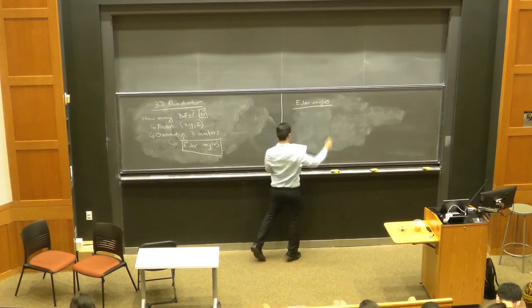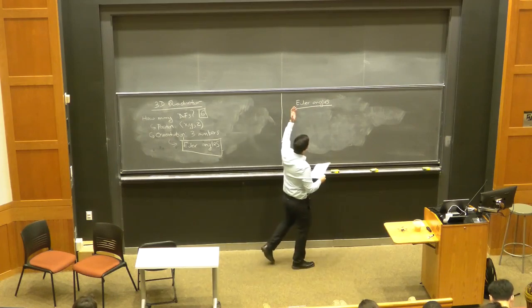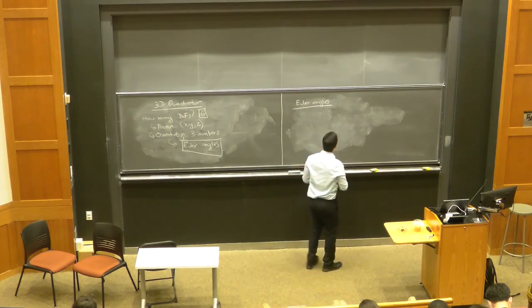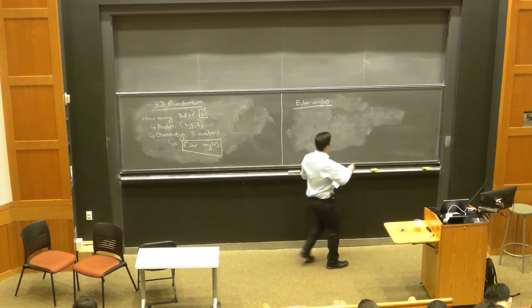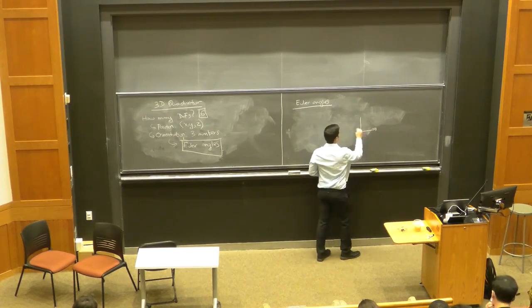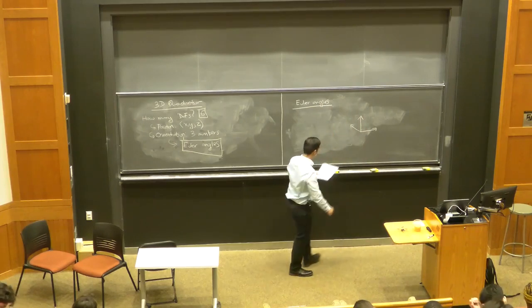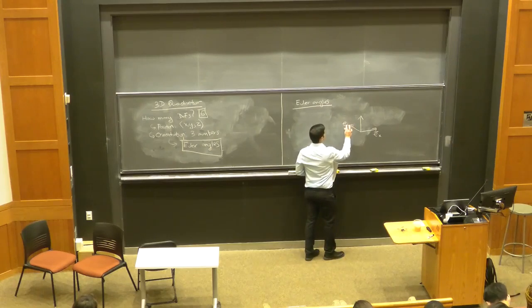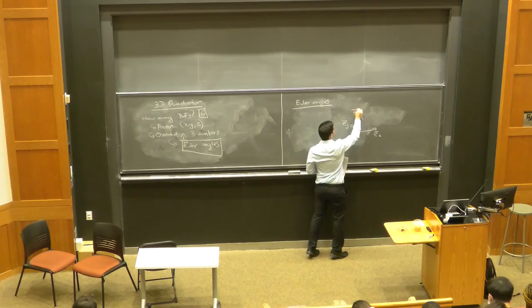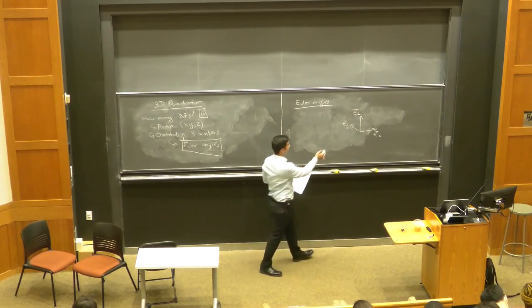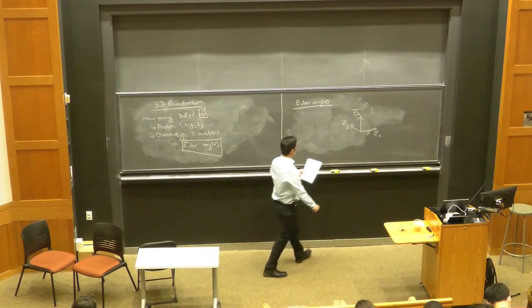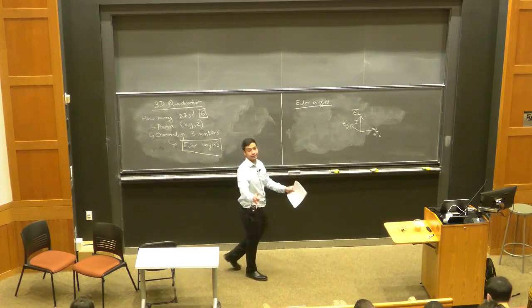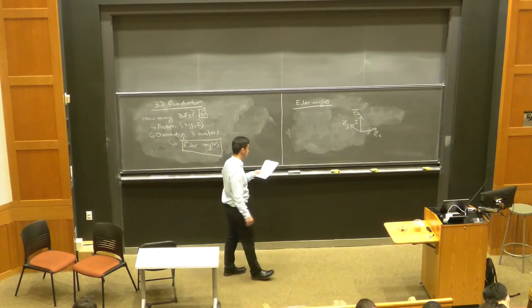Okay, yeah, like I said, this is one way to specify orientation of some 3D object. The way this is going to work is we're going to first define some reference frame. These are three directions, EX, EY, and EZ, that form a right-handed frame. So you can see that EX cross EY is EZ. I'm going to label this frame as I. So I is our inertial reference frame, some reference frame that's just attached to the ground, attached to the room that the drone is going to be flying in.